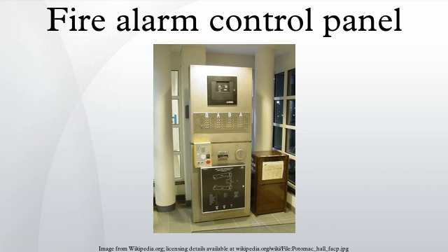Boolean Logic. This is the part of a fire panel that has the largest variation between different panels. It allows a panel to be programmed to implement fairly complex inputs. For instance, a panel could be programmed to notify the fire department only if more than one device is activated. It can also be used for staged evacuation procedures in conjunction with timers.